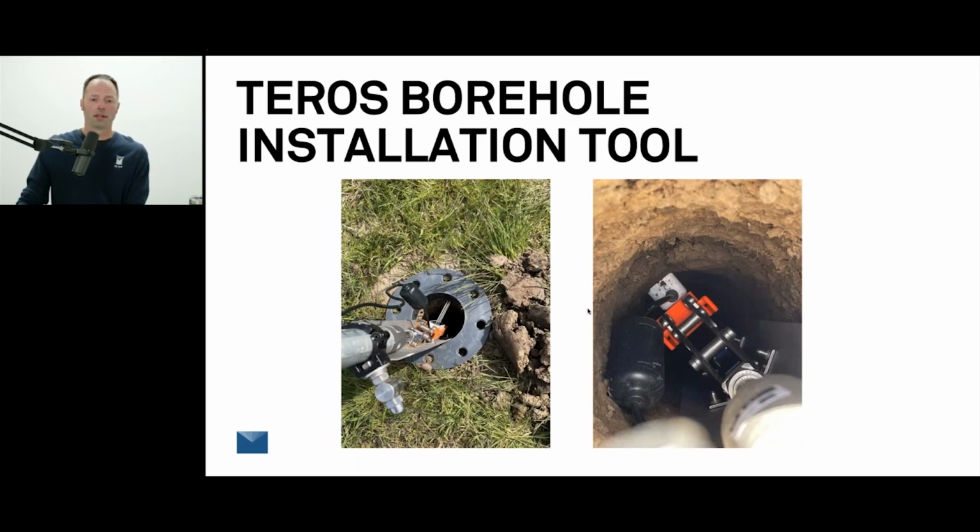And here you can see this is what you want to go for. We don't want to see any of the silver pins, of the metal pins here. You want to get your sensor flush right up against here. This way you know that you're getting the best possible contact with the soil. So this is step one. And the installation tool is really good at doing this. It's got a little pusher adapter even, so that if you don't quite have it in there, you could just get a little more leverage and get that sensor fully flush.